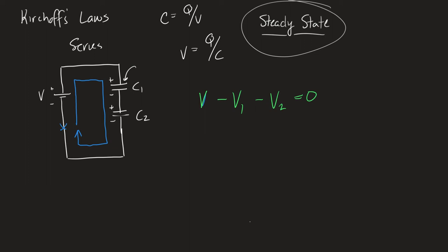Now, we only had one loop through the circuit, but it creates this relationship. Now, the next step in trying to solve a circuit after you've applied the voltage loop to your circuit is to check and make sure that every circuit element has been taken in by the loop you chose. Now, this is a simple circuit. There was only one possible loop through the circuit, so we got every one of the elements. So now that we have accomplished that, we have made sure we've taken in every circuit element here.